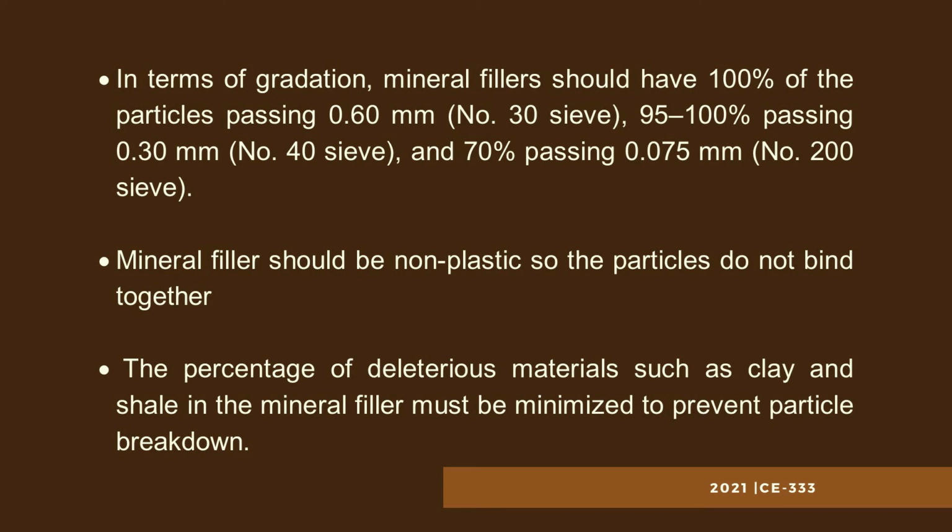So mineral filler should be non-plastic, so the particles do not bind together. So dapat daw kapag nagagamit tayo ng mineral filler is non-plastic siya, para hindi magdidikit-dikit yung particles ng mineral fillers natin. And the percentage of deleterious materials such as clay and shale in the mineral filler must be minimized to prevent particle breakdown. So kapag gagamit daw tayo ng mineral filler, dapat limited lang kapag mag-a-add tayo ng mga deleterious materials such as clay and shale, para